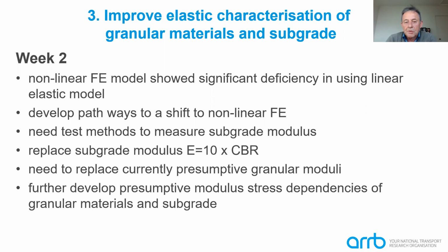There's a need to develop methods to measure subgrade modulus. We don't have those values at the moment. I mentioned that in week 2 as well. Concerns about how you prepare specimens at the right moisture content for testing. We have a simplified approach for estimating subgrade modulus, and it has a major influence.